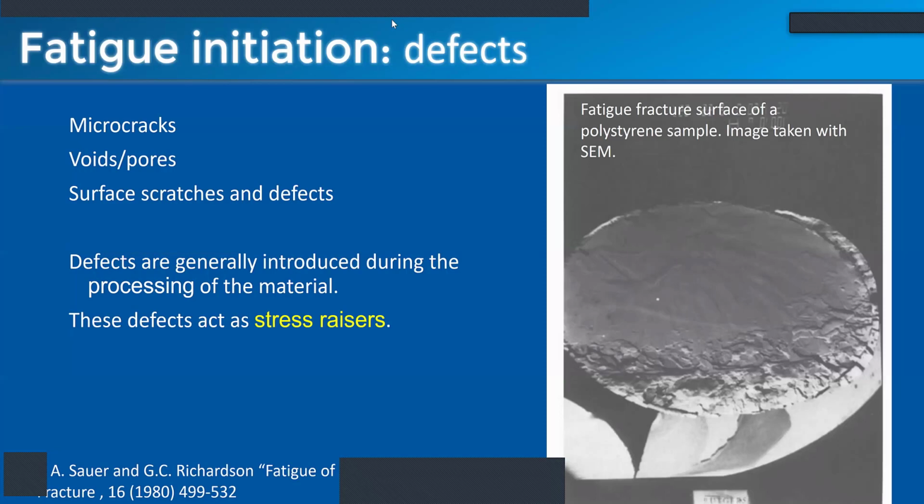I've got polyethylene. And polyethylene's monomer is the simplest type of monomer you can have. It consists of 2 carbons and 4 hydrogens. It's shown there in red. That is called the monomer of polyethylene. And when it's actually in monomer form, so when it's not polymerized, there's a double bond between the carbons here, which satisfies the octet. And we'll talk about how monomers polymerize into long chains in a future lecture. But just be aware whenever you see a monomer, most of the time there's a carbon-carbon double bond there. And that double bond is broken to form the polymer chain.